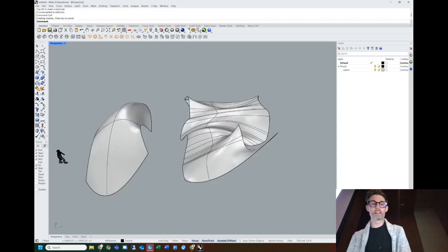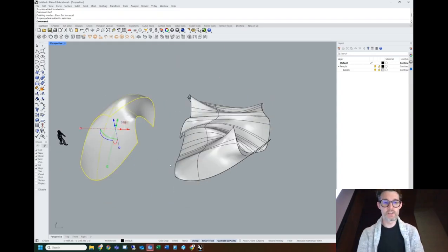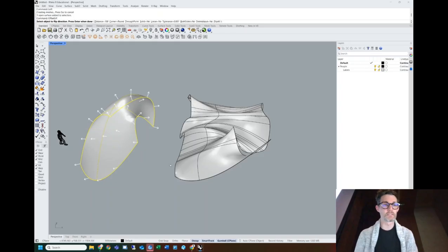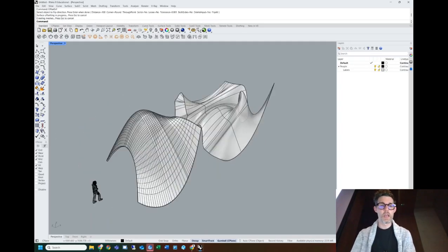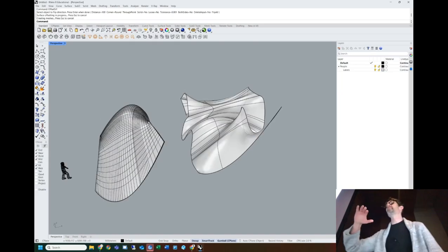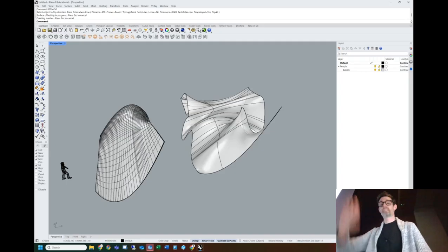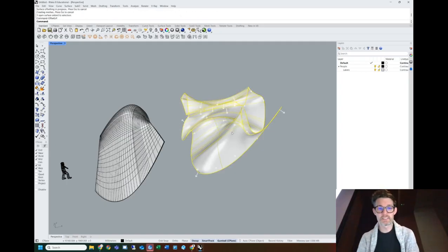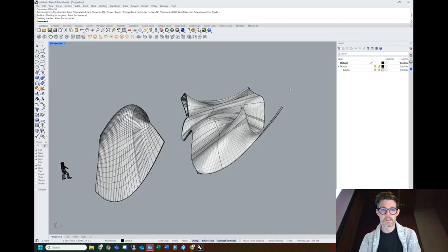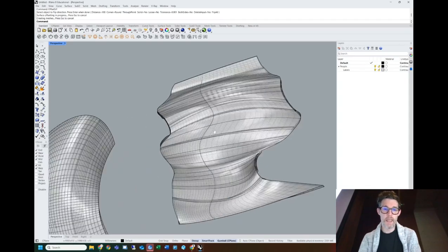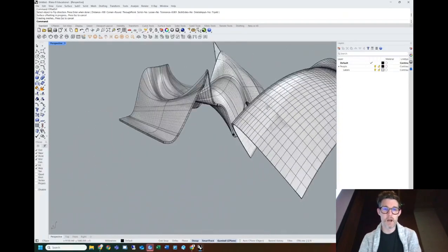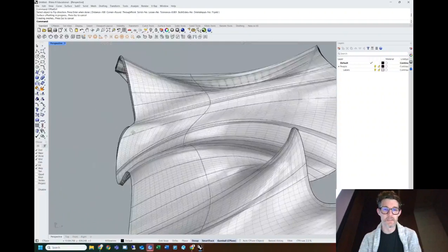Where this gets really obvious is if I select this, or did this last week, I'm going to offset that surface to make it thick. Maybe 100 mil, there we go. And already, do you see how it's multiplied up the number of those black lines in order to create that surface that has thickness? If I do the same with this, the number of black lines becomes much more complicated.